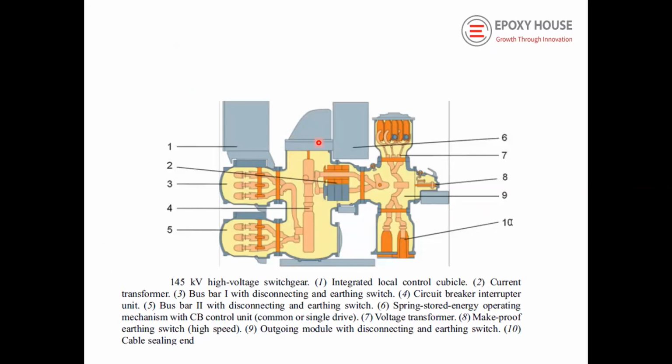See, this is a circuit breaker, in a double bus bar scheme where 2 buses are there, and the connection is coming from a feeder line. The feeder line is coming through the circuit breaker like that. It is connected to the bus bar like this. See the 3 phases. Now, in between that, there are disconnectors and switches. And here this current transformer can be within the enclosure of the circuit breaker, or it can be a separate enclosure, depending upon the customer and the maintenance requirement. Now in this case, it is inside the gas chamber.